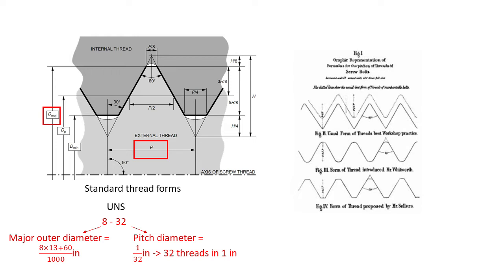So for example, if you want to move something really slowly, you'll use a smaller thread pitch and a larger thread for bigger movement. The same understanding is used in power screws, which are used to transmit loads. You may have seen this in motor drives with lead screws or power jack. Lead length is exactly the same as the pitch that we just talked about. It's basically the linear distance that is generated from one rotation.